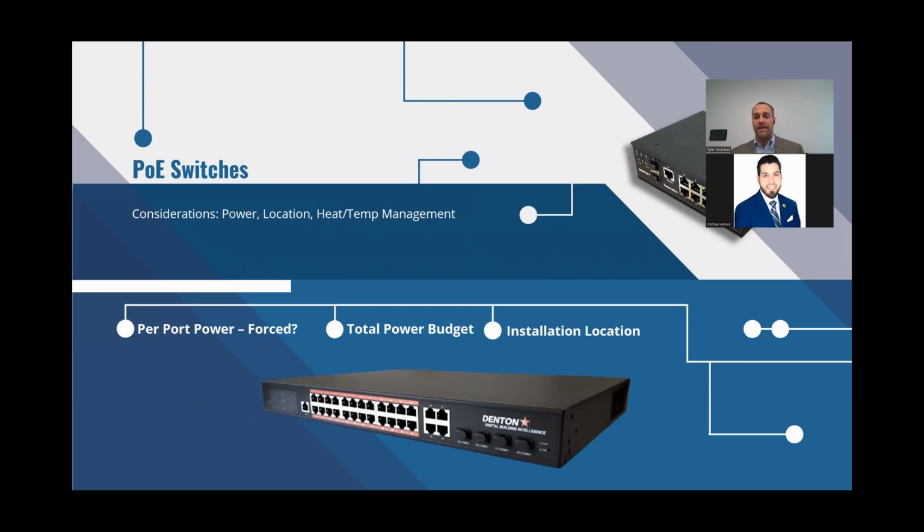So I'm going to dive right in to a PoE switch. With PoE switches, when you're doing lighting and automation, it is not the same PoE switch that you would use for, say, a PoE camera. You really need to understand some key items around power, both the power by port and the total power budget. And there's some key considerations about the installation location that help drive both the selection of the form factor and the power. So today, I actually have some products here with me.